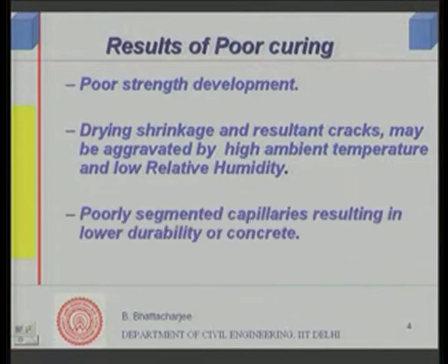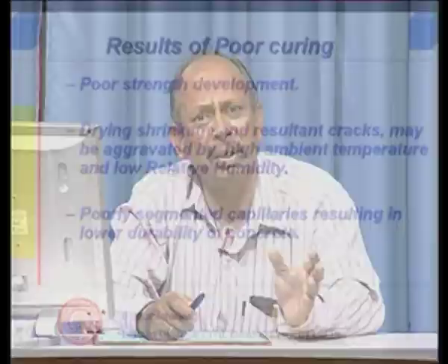So, this is an important issue. If I do not do curing properly, I can have drying shrinkage cracks. Sometimes they are only fine cracks, crazing at the surface, but aesthetically they are poor. Sometimes, in very thin sections, drying shrinkage cracks can be through and through cracks. Of course, there are other ways of tackling these cracks, but curing helps in preventing such cracks.